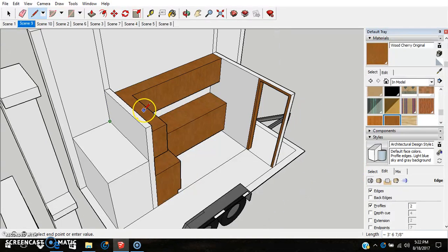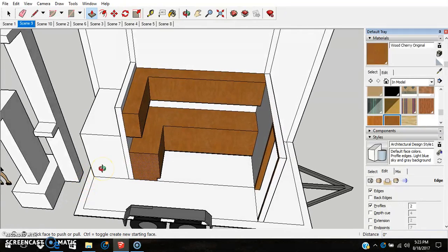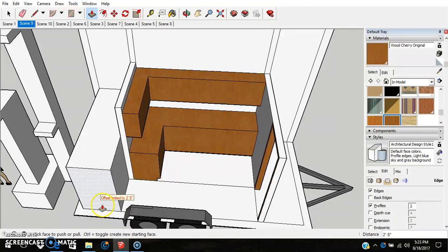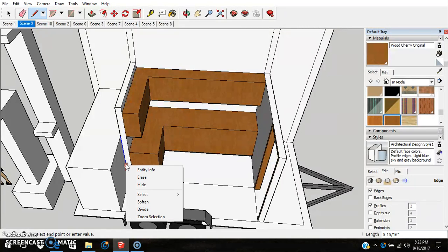Let's back off a little bit. One thing to get out of the line, you can always go to space. That's a neutral setting, so you're not going to be messing with lines or end up making a mess somewhere in your model. All right, we'll orbit here. We'll pull this out. This will be the stairs coming out here. So we need to determine what sort of height we're going to have for those. We'll use the line tool over here, push L.